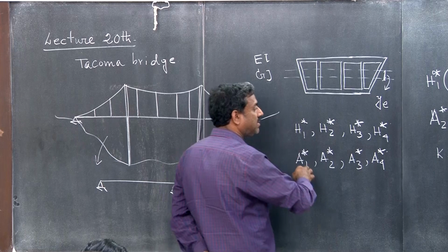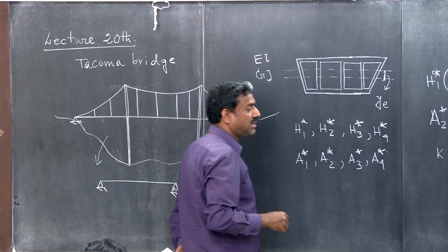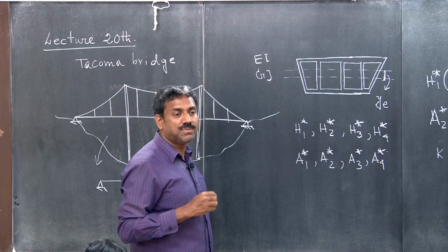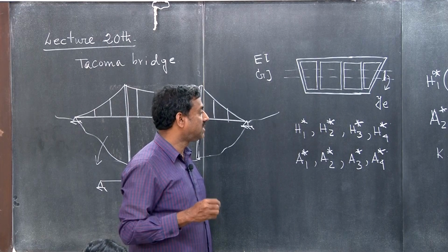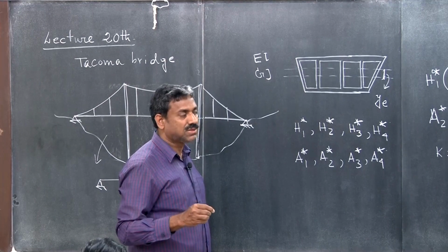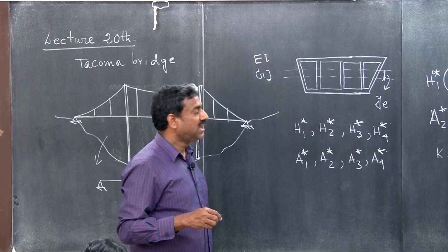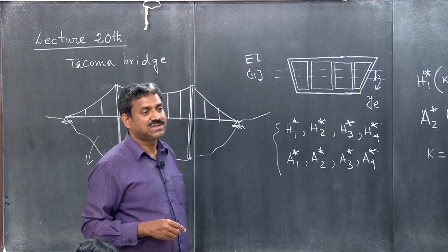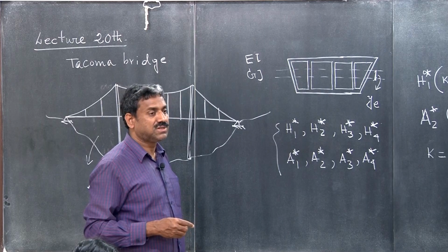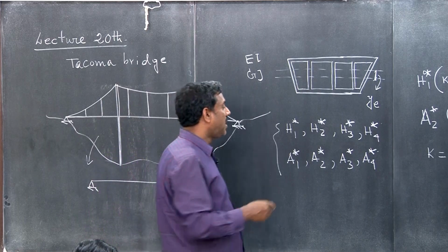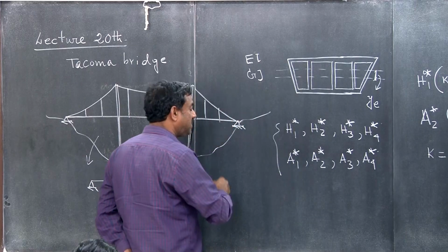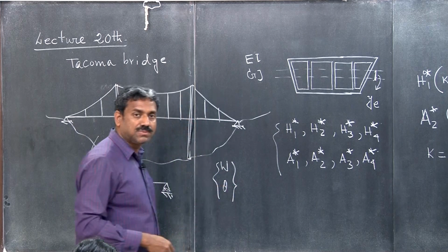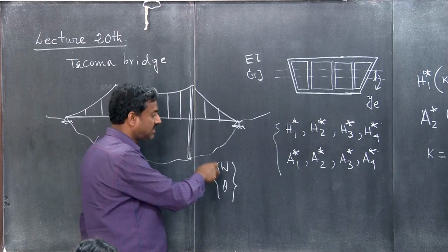Out of all these flutter derivatives, only two will remain. These flutter derivatives help in expressing the aerodynamic loading on the structure as a function of the displacement, the response of the structure. All these flutter derivatives we have to find through experimental investigation or a computational fluid dynamic simulation involving fluid structure interaction. Here there was a 2 degree of freedom flutter model, involving the vertical deflection of the deck as well as torsion. We denote these as W and theta.